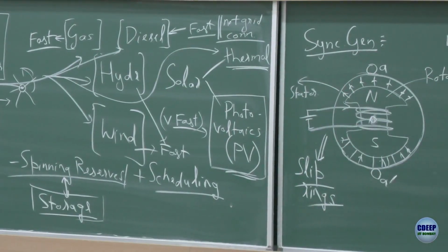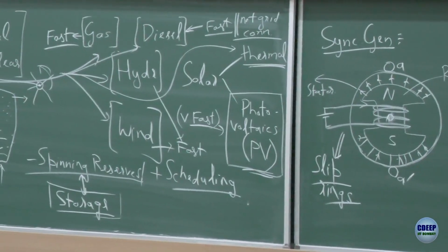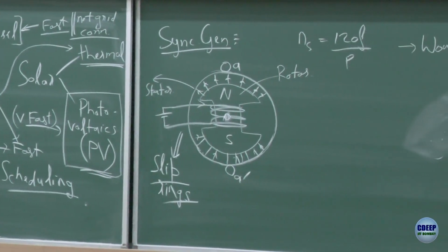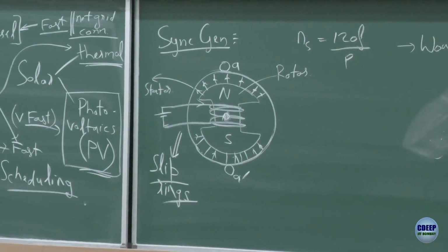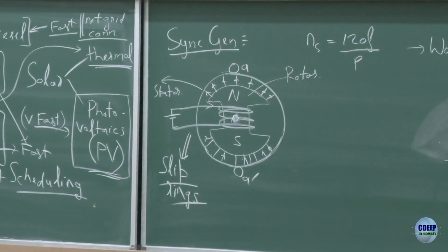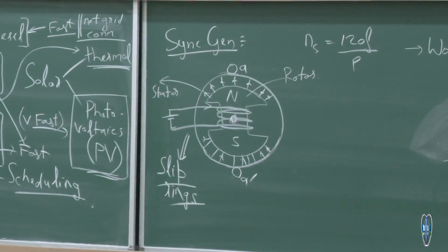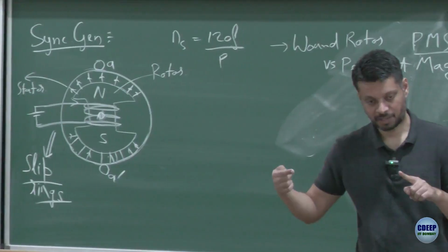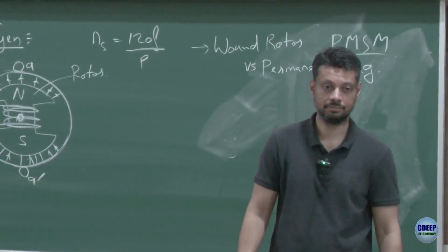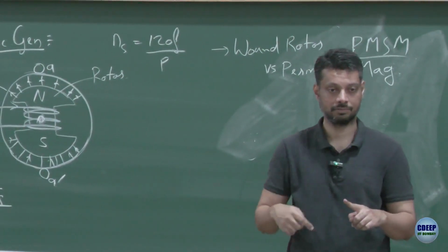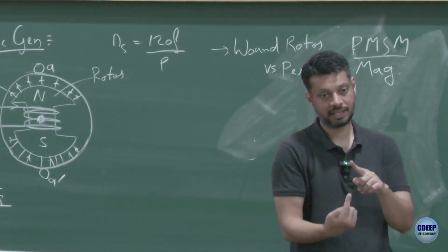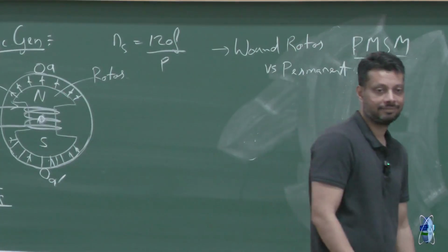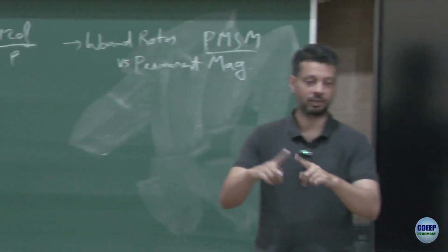The wires will never complete the circle. That's why we are putting slip rings. So they're connected before, right? And then you move this and then you connect again there. You take the wire from inside the rotor and connect. Don't take it from outside the rotor. The rotor is hollow, take it from inside and connect to the slip ring. Your wires will not cross. You can do it.